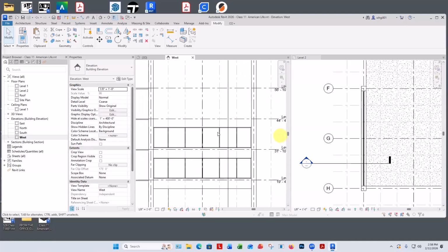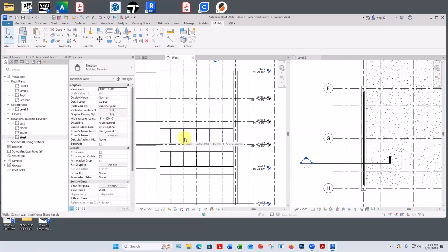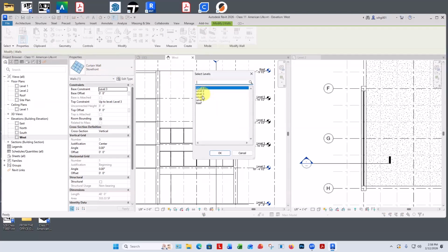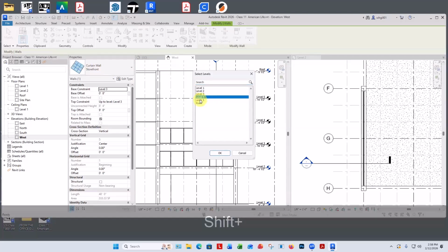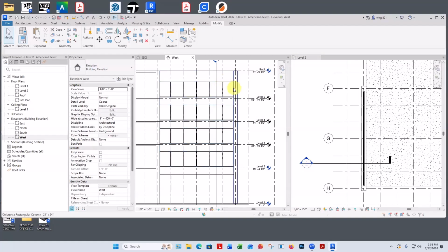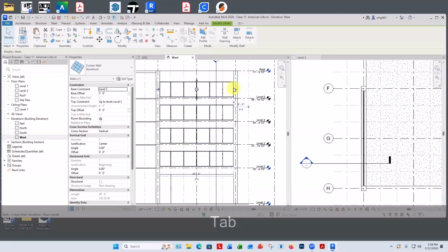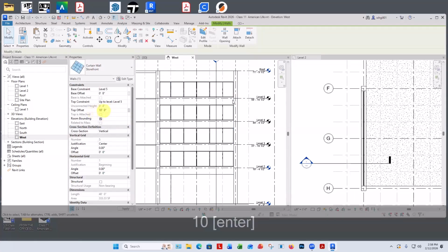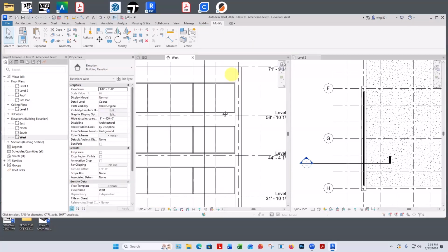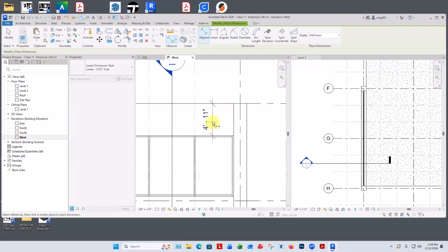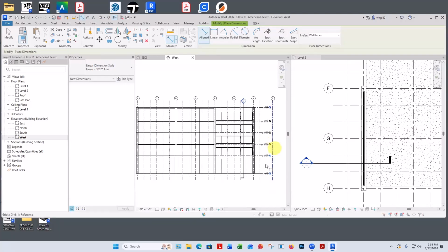So I think we can comfortably copy this up to levels 4 and 5. Copy, paste, align the selected levels, 4, shift. Okay. And then this one, we're going to make another foot higher. 10 feet. Okay, and that's 4'11", and we said it was, I think, 5 feet, or 4'10", so that's fine.